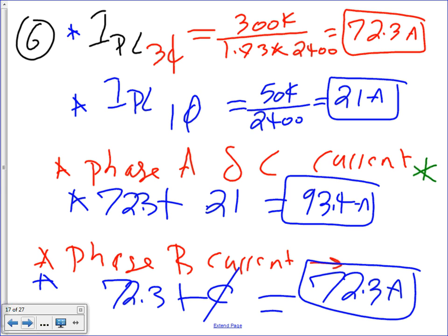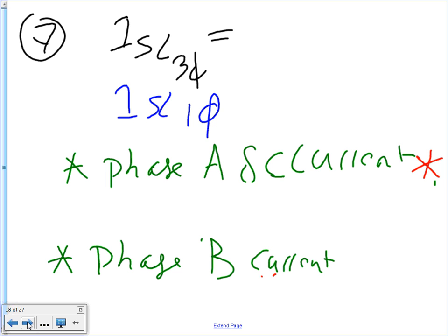Okay, now when we size the fuses and when we size the conductors, we have to take this into consideration. That's all done. You're going to take into consideration the size, so there will be two phases bigger size-wise, fuse and cable, than the other phase. And if you guys look at the utilities, they do it all the time. Okay, so let's go to size number 7.